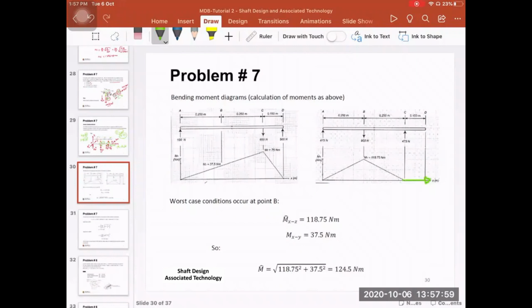Okay. So you see here on the right-hand side, we have here the vertical plane. So we have X here, and then the vertical plane was Z. So here is the moment in the Z direction. Then on the left-hand side, we have XY plane. So this is the moment in the Y direction. Okay. So in the horizontal plane, as I said, we have here a force that is 500 on the right-hand side pulley. And then there is a reaction force at this point, another reaction force at this point. These two reaction forces are RA horizontal and RB horizontal, okay?